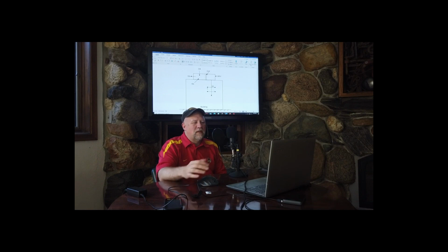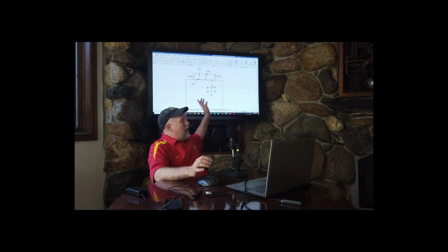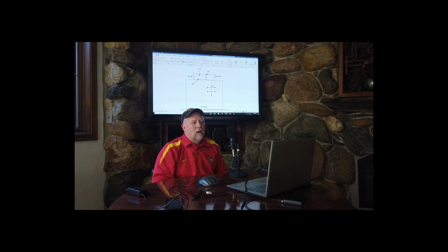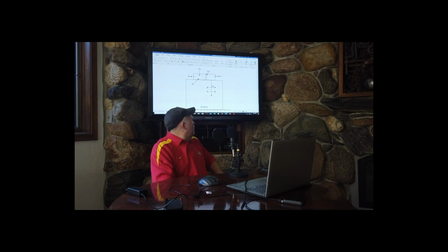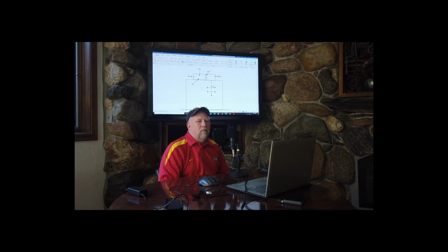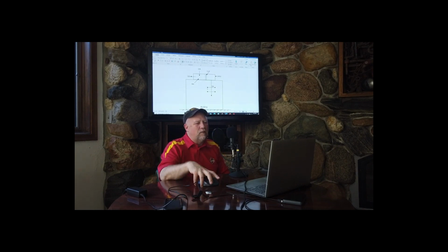The way we start this, the design process. First, we'll calculate all those space heat gains. That was the last part. That was last week's. We add up all the sensible space loads. Now, and this is why we only looked at sensible space loads. In terms of real world practicality, at the room level, most of the load is sensible. In other words, we don't have a lot of moisture production. There's only two sources of moisture production in an office space or a classroom.